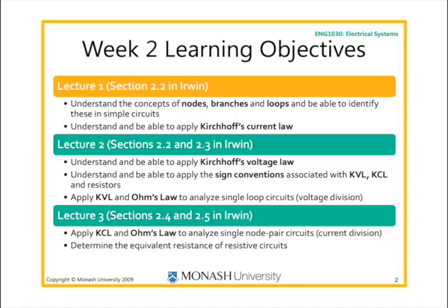Are there any circumstances in which that voltage can be different on the same bit of wire? Not really. Well, not when we're making an idealised model. Yeah. Actually, absolutely it is. Because a real wire will have some resistance. The question is, if that resistance and the bulb are 10 ohms, 20 ohms, 1,000 ohms, and it's 0.1 ohms per metre, then it's pretty insignificant. So yes, it's an idealisation, but just to show I wasn't like, there you go, free coffee voucher for asking a question. There you go, excellent.